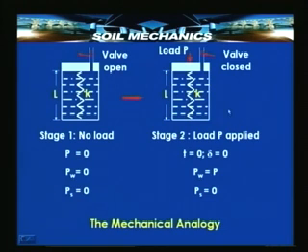So, at this stage where the valve is closed and load is applied, the load simply is carried by the water. So, the load carried by water is equal to the total load P applied, and the load carried by the soil skeleton, the soil solids, is now 0 as before.